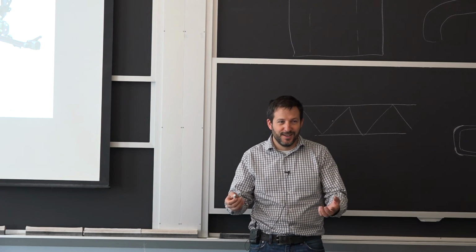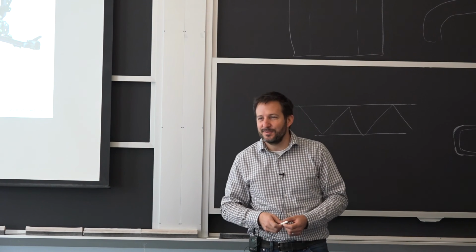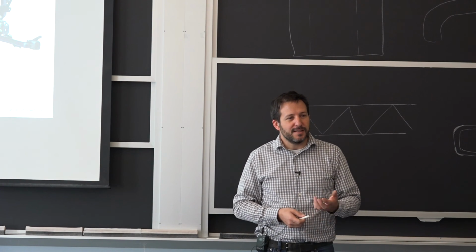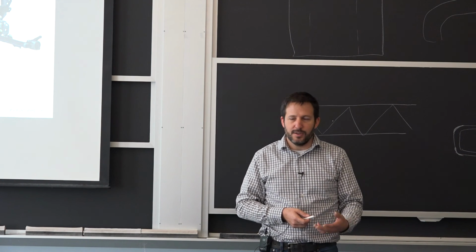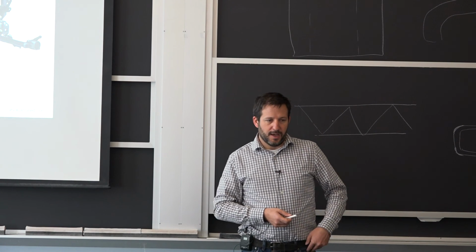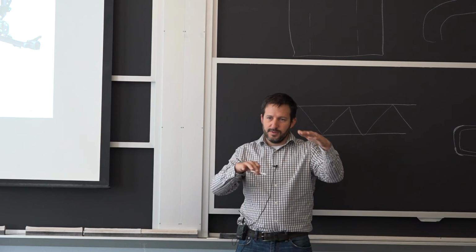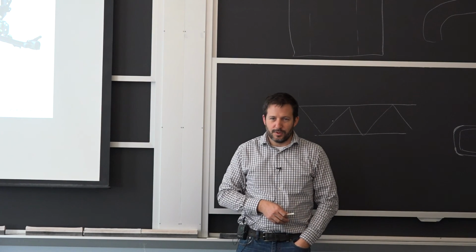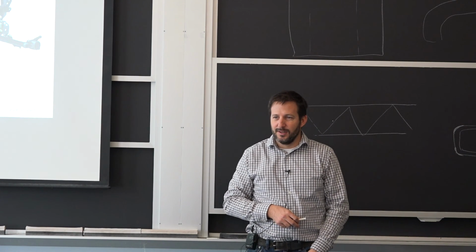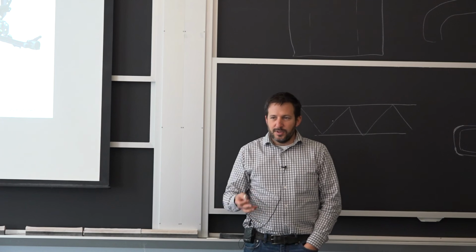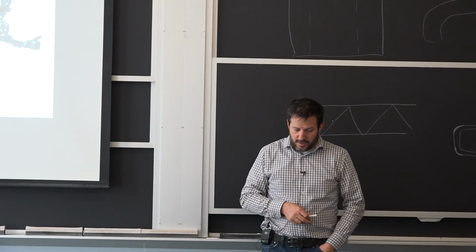You go to a station, they have these beams. They're there, and yeah, it's steel, it looks rusty here, but you don't know if that steel was made to any specific specification as to where it can be welded. And a lot of times they're big sections. You have different floors involved, and the load, the design of the station may have changed over the past 70 years. And when you go and try to connect to an existing structure, you have to do these tests to make sure that you can qualify.